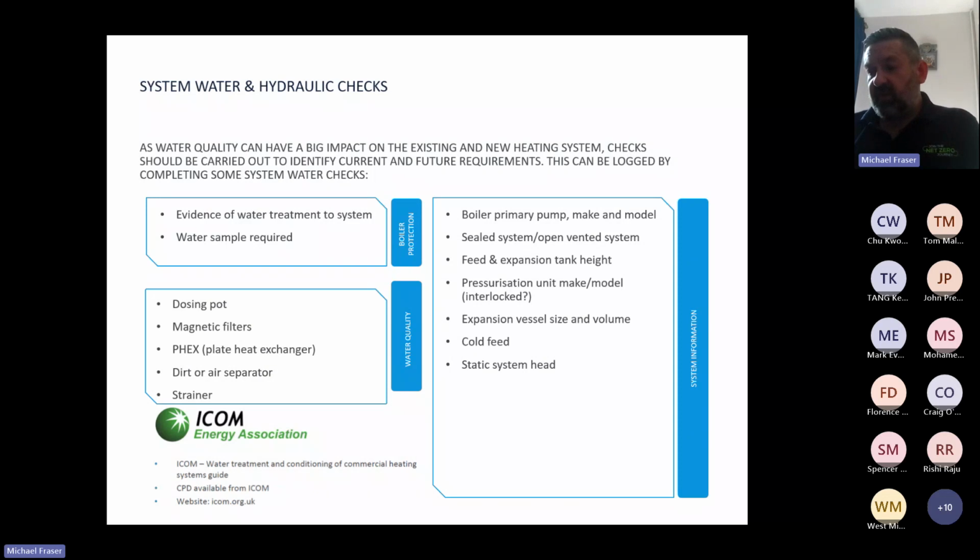This is most important, as we need to know the pressure in the plant room. Our maximum for our appliances is 6 bar. So if you've got a tall building and a basement plant room, this could become an issue. So then you can look at using a plate heat exchanger, or even multiple plate heat exchangers on different floors, as they can take up to 40 bar.